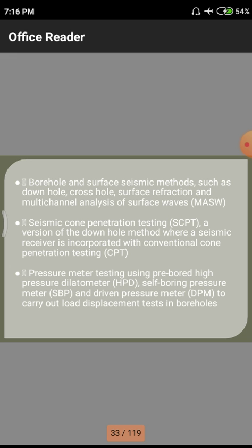If density is more, these waves will go in a very slow manner, and it will take a huge amount of time. If the density is very less, the waves will flow easily and reach a certain point in a shorter span of time, so these seismic methods are used for the calculation of the density parameters of the soils. Next, we have downhole methods and crosshole methods.